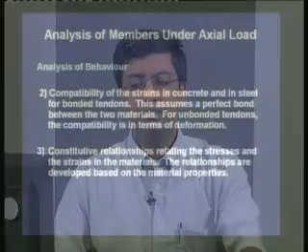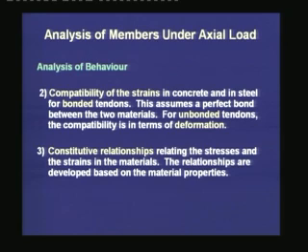The second principle of mechanics is the compatibility of the strains in concrete and in steel for bonded tendons. This assumes a perfect bond between the two materials. This is another very important principle that we are assuming, that the concrete and the prestressing tendon and any other non-prestressed reinforcement, if they are present, deform together.